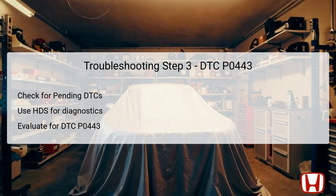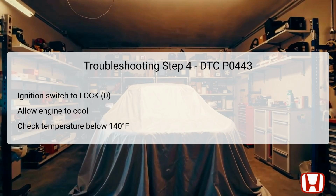The technician should then inspect for poor connections or loose terminals at the purge valve and PCM to ensure reliable performance moving forward. A fourth step requires turning the ignition switch to the lock 0 position. This action ensures all electrical systems are powered down, allowing technicians to work safely on the vehicle.